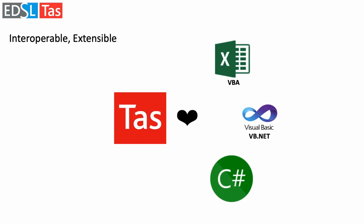So it is extensible, as I mentioned. With Excel, you can write VBA scripts to automate either the creation of files, modification of files, simulation, or extracting results. And you can do the same thing with VB.NET and C#, with C# being used in TAS GenOpt for the optimization and parametric analysis.